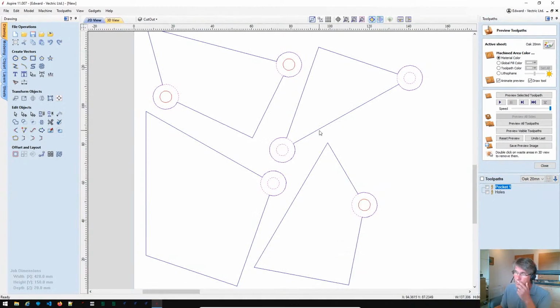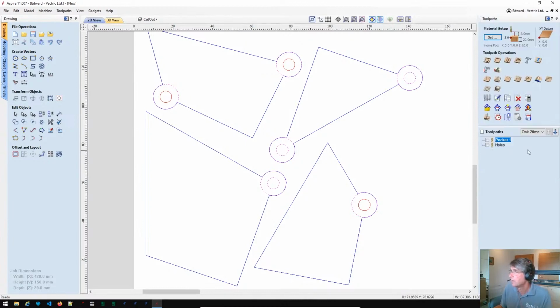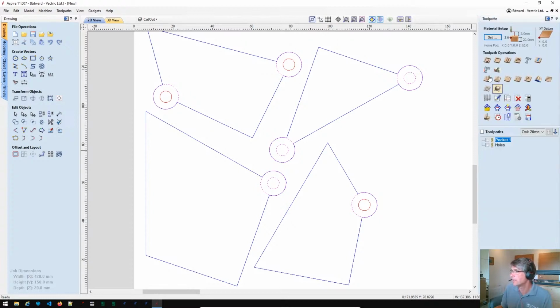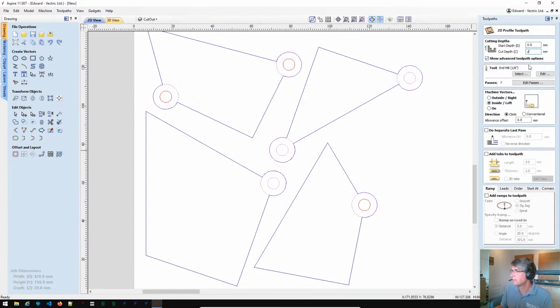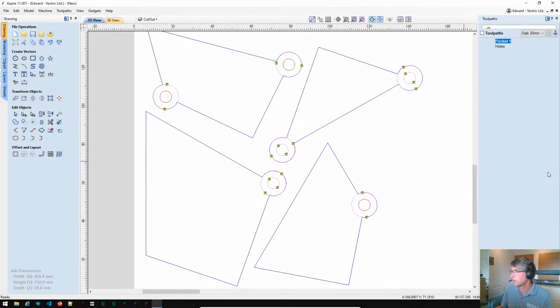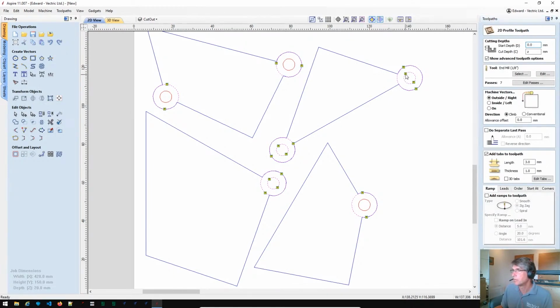Okay, so the final stage then is the cutout pass. Now we do need to remember, this time profiling, same settings all the way through, down to Z. We do want to cut, not pocket, what we're doing here, profiling. Down in Z, we do want to go outside this time. We probably want to add some tabs, just a couple of tabs to make sure, depending on your hold down mechanism. We don't need that many tabs.